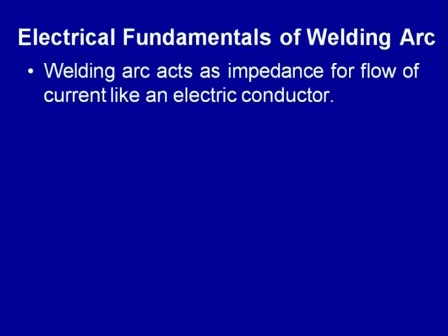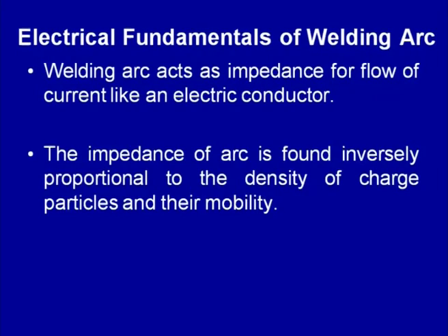So, if we see here in the electrical aspects, we know that the flow of current is important for stabilizing and for having a smooth welding arc, so that the heat can be generated for melting the faying surfaces. But when the current flows, the gap between the electrode and workpiece mainly acts as an impedance for the flow of the current, and this resistance for the flow of current results in the generation of heat.